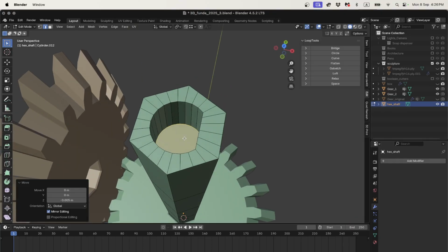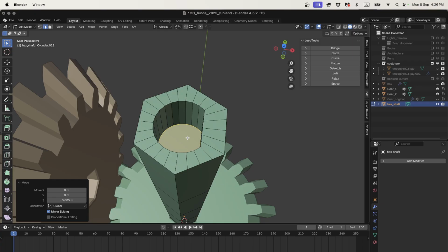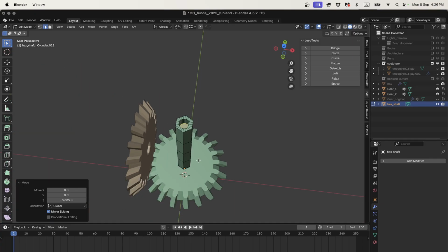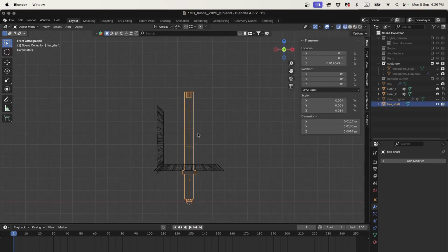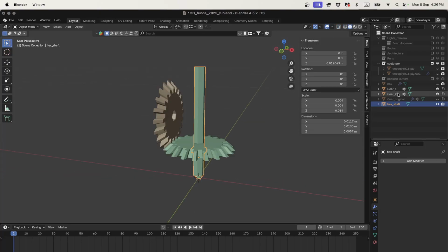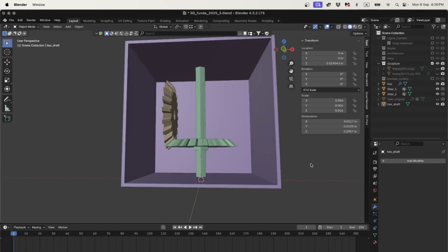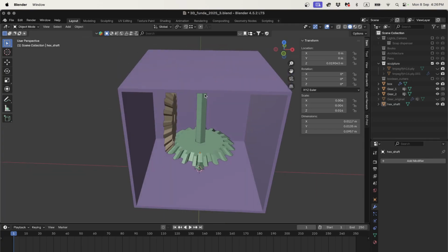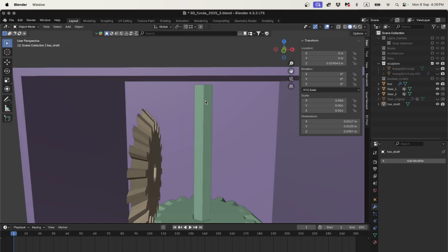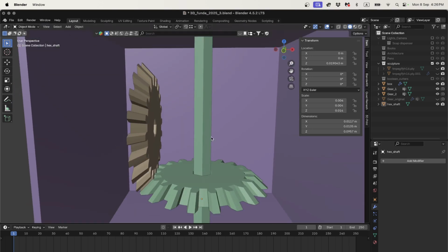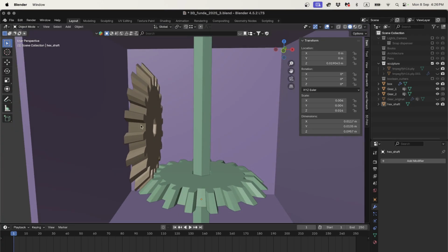So now that's like a 5 millimeter hole. Okay, let's leave it at 5 millimeters, and then we'll see if we need to adjust it. We'll leave it there and see if that makes sense. So there's our hole. Okay, so now we've got, I think, something pretty good. If I bring back the box, that all makes sense. So now this can spin, and we've got a hole up here so that if we have something coming through here, it'll fit into that D shaft hole and inherit the rotation from this shaft. Okay, so let's do the same thing here.